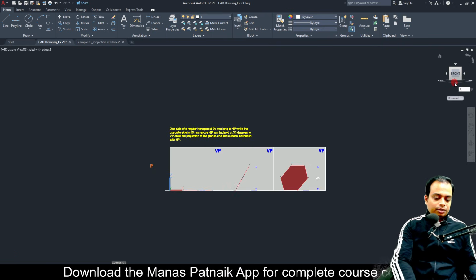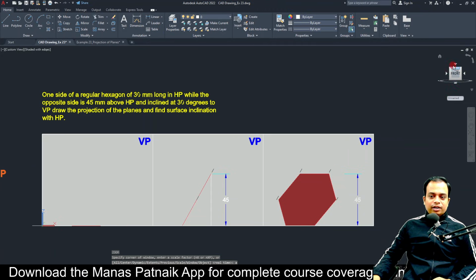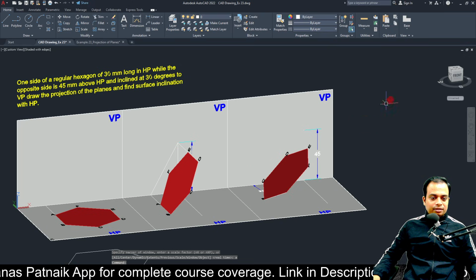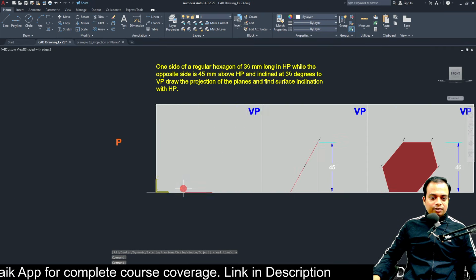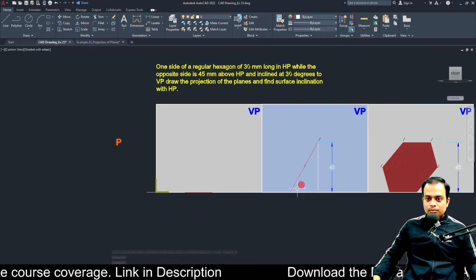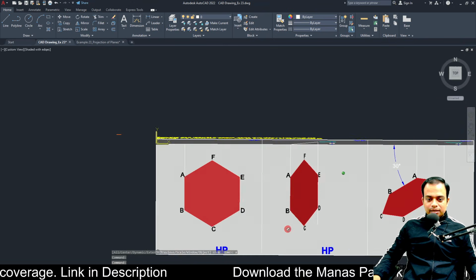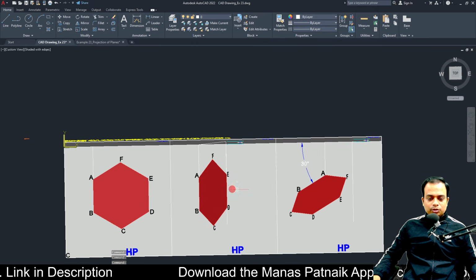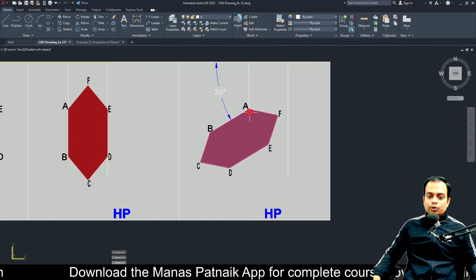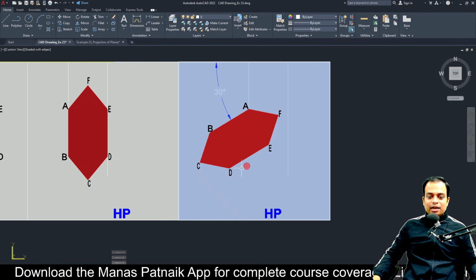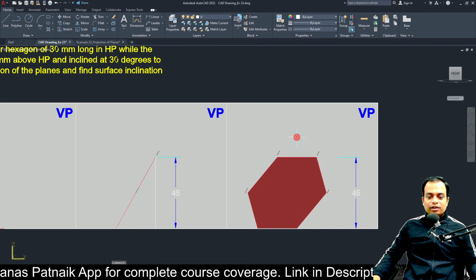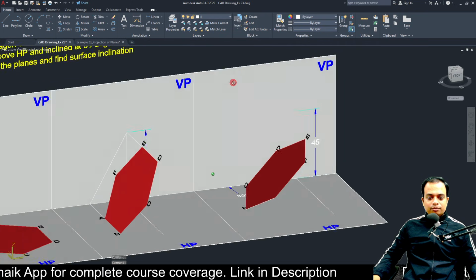Okay, orthographic projections. Have a look once again. This is the front view. There is something right here. There is something over here. Okay, it will look like a line in the front view, and that same line has to be recreated in step number 2's front view. And this is how the top view looks like. And this is the final top view, right? In the final top view, we've ensured that the edge is making an angle of 30 degrees with the vertical plane, and this is going to be your final front view. Think about it. It is a beautiful question.